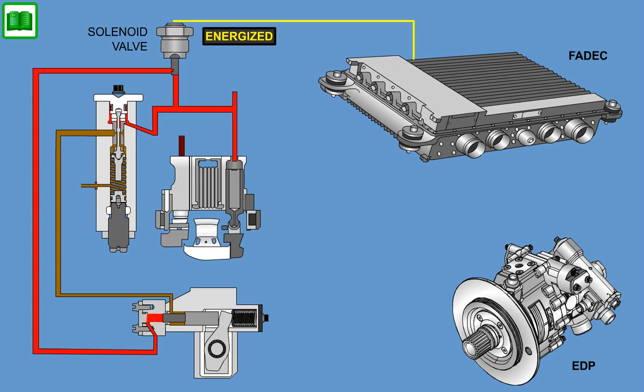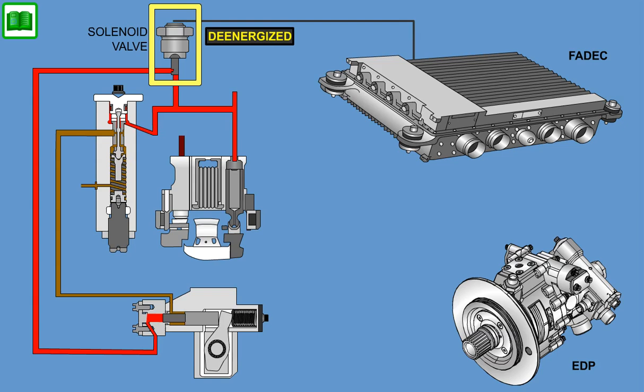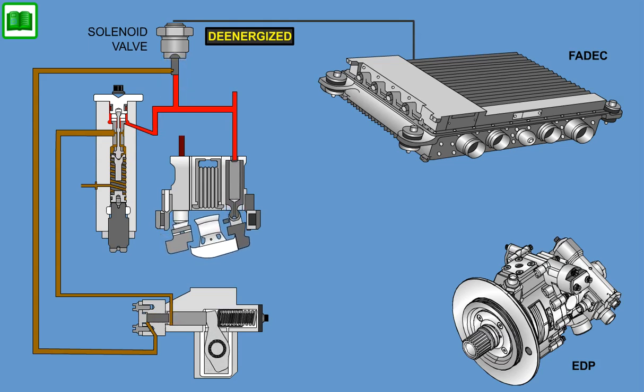When the applied voltage to the solenoid is removed, the de-energized solenoid valve returns to the normally closed position, venting the pressure applied behind the stroking piston back to the case. Discharge pressure is blocked at the solenoid valve, and normal pump operation via the compensator resumes.